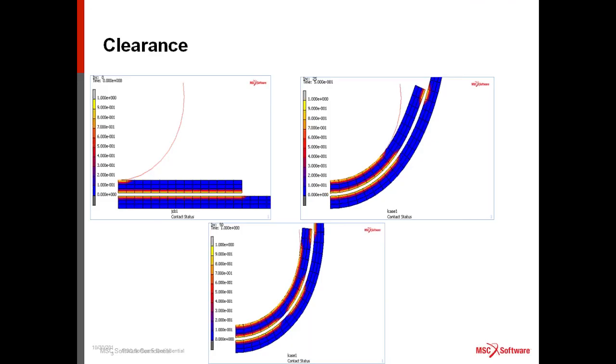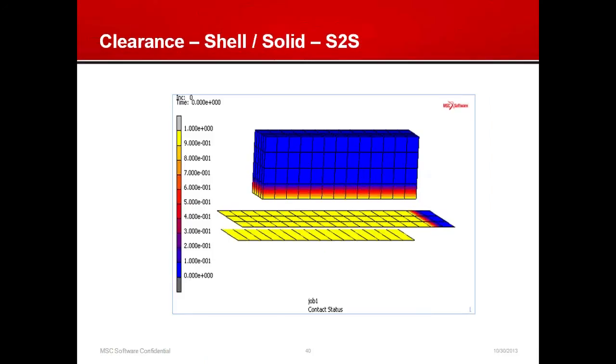And we can do this as well for large rotation type problems. Here's a model. It has initially a large gap. Of course, that's much larger than the gap clearance or the default contact clearance. And you can effectively rotate these two sheets, and you see that the initial gap tolerance is maintained.